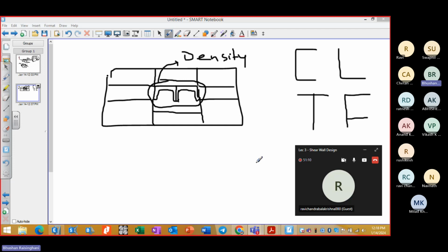So protection of the staircase is important, and enclosing it with a wall will help us to avoid that. But it is a solid wall from top to bottom, so we don't have flexibility of any opening in other directions. That's why people keep it separated from the architectural point of view, but from the structural point of view, it should be protected.